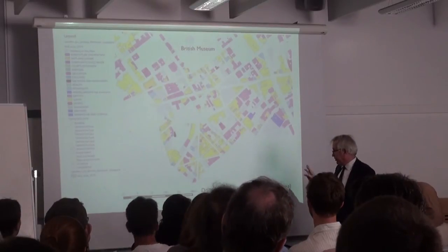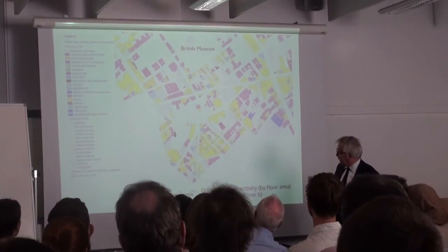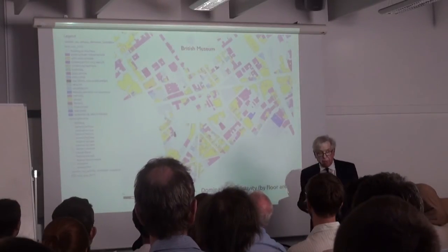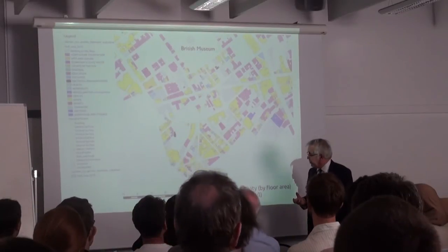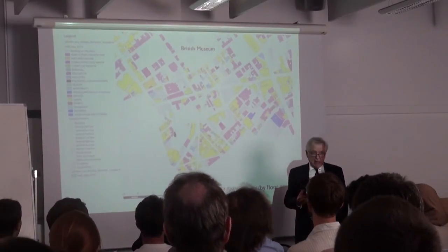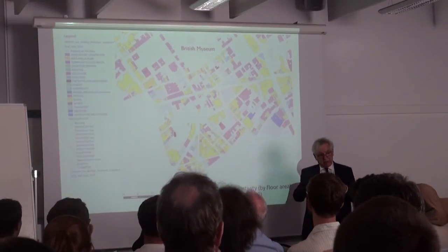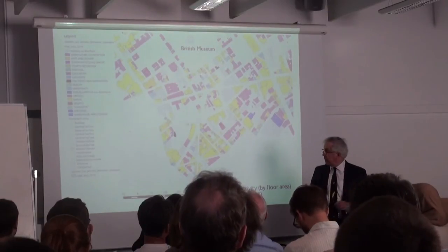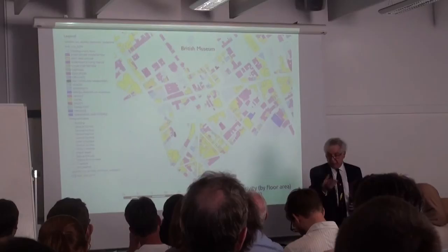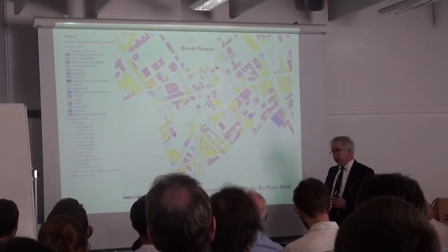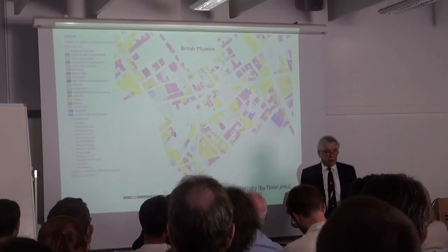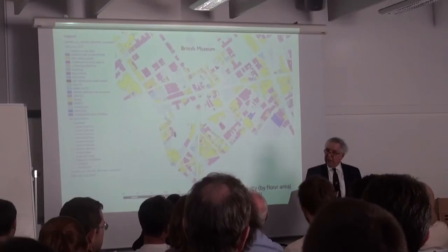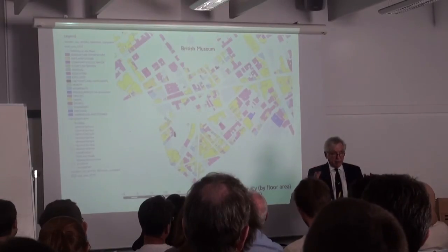And this is the dominant activity, color-coded, on the ground floor of, they're not buildings, we've defined a special unit which we call self-contained unit. The importance of the self-contained unit is that it has a clearly defined envelope for which we know the energy use, and we know where the heat is being lost or gained, and also that it doesn't cut any premises, so that if a shop has gone next door into what you might think of as another building, we would include the two buildings together in one self-contained unit.